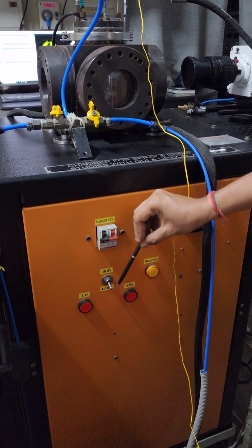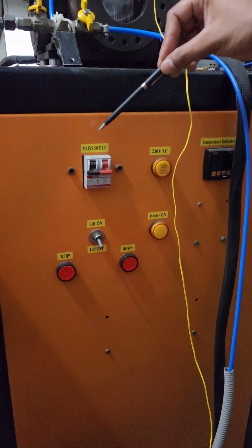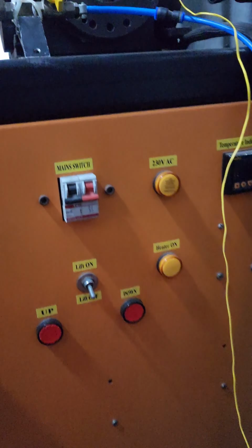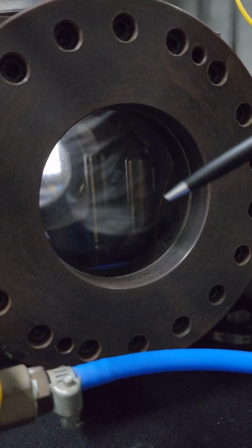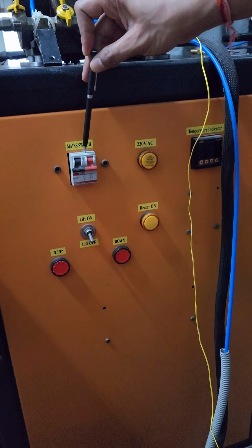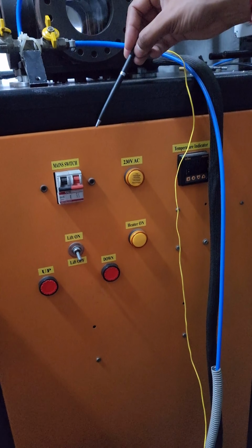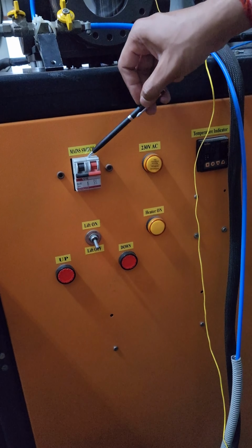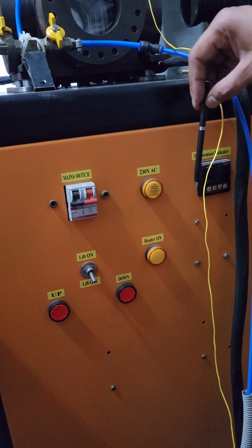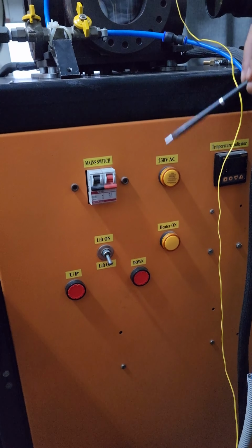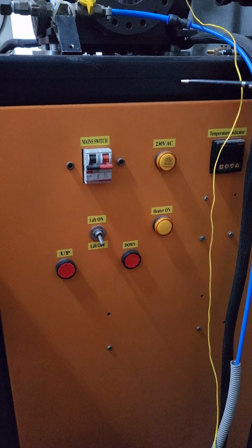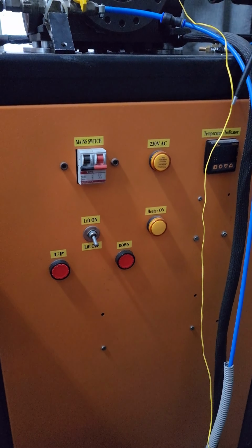This is the control panel for the constant volume combustion chamber. The chamber comprises 4 heating rods that heat up the gas inside the constant volume combustion chamber. This is the main switch to turn on the heating filament. The heating filament is connected to a thermocouple and works based on the feedback signal. Whatever temperature you set, the feedback signal provides the current temperature in the loop, and on the basis of that it turns on and off periodically to maintain the temperature.